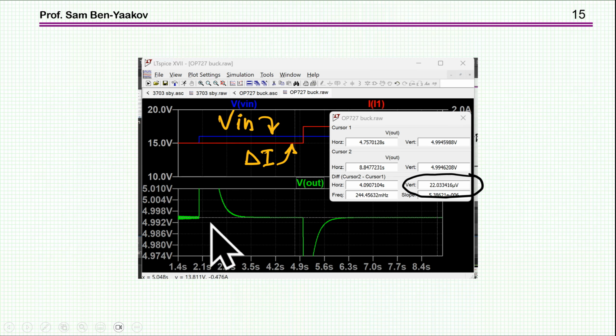And what we see here is that after the transition, that is after the step, the DC value comes exactly to be the same. This is both for the V-in disturbance and also for the delta I disturbance at the output, okay? In both cases, it's coming back to the same thing, and in fact, we are within microvolt differences between before and after.